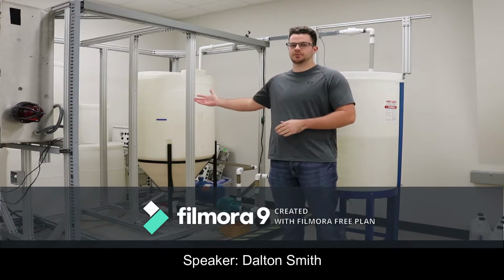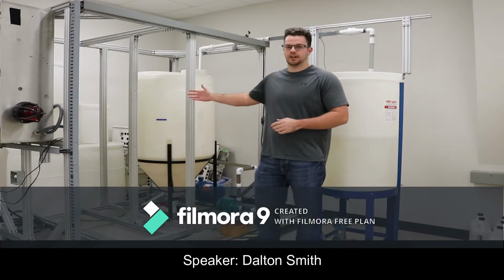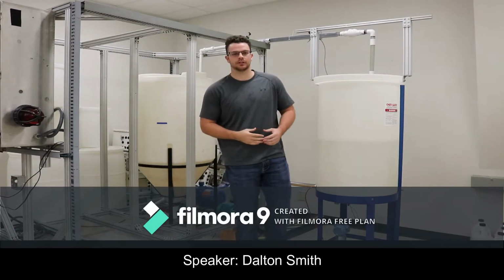This system contains a supply tank, which distributes fluid by means of a three-phase pump to a return tank. The return tank has a single-phase pump to return fluid to the supply tank, creating a closed-loop system. A flow meter is in line with the flow to allow the user to determine flow. A differential pressure cell is fitted below the return tank to allow the user to determine height of water in